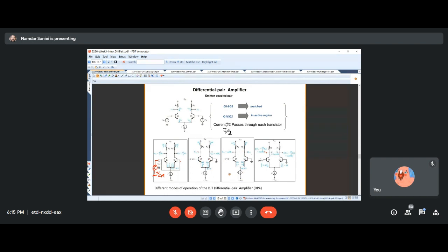And in that circuit, the bias current would completely be going through one versus the other branch. So one branch takes all the current and the other one is off and does not pass any current. So depending on what large signal we are applying, if it is positive or negative, one of the two transistors is going to be off, the other one is going to be on.